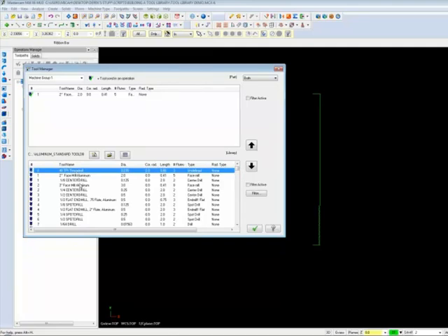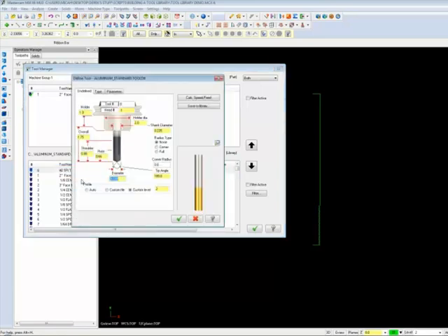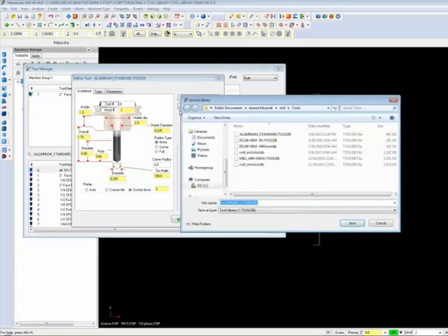Since this tool is capable of cutting most any material, what if we need this tool for our steel or plastics library, but don't want to go through the hassle of entering all the parameters all over again? Select the 40 thread per inch thread mill, right-click, and select Edit Tool. Click the Save to Library button. Select another library to save the tool in, and click OK.